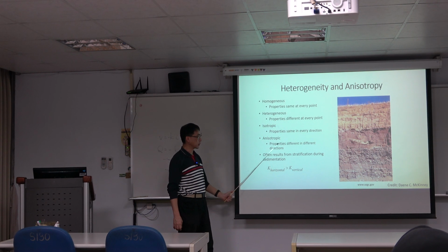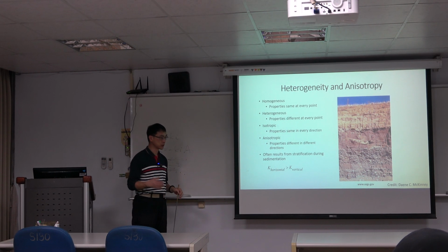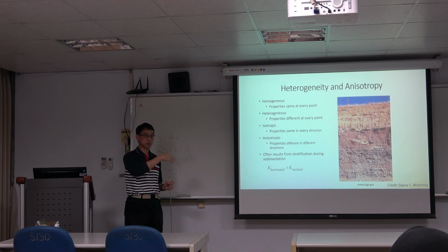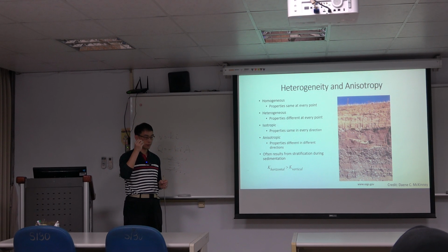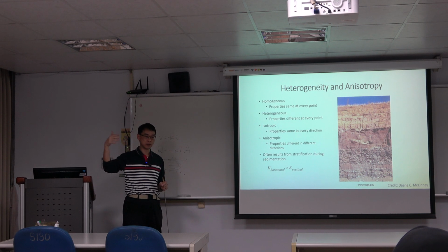And anisotropy is also quite largely observed because, as we mentioned, of the deposit environment. If your particles have a shape, not just a grain size, they might have a somewhat different shape. They will have their preferential deposit directions, and this deposit behavior will make your flow behavior different.